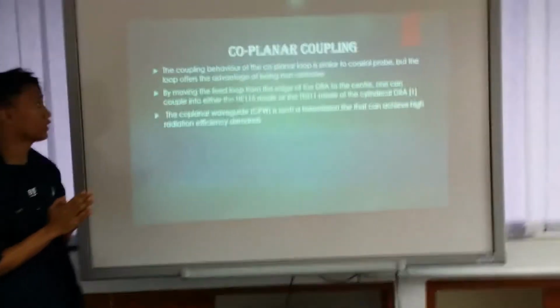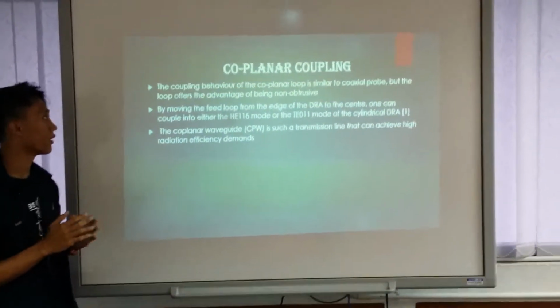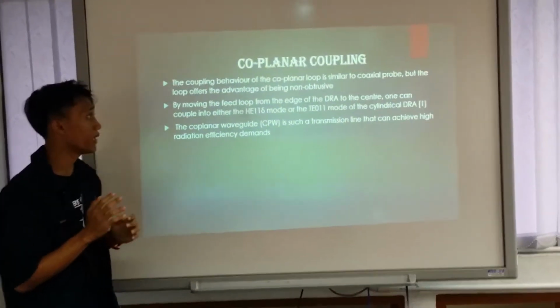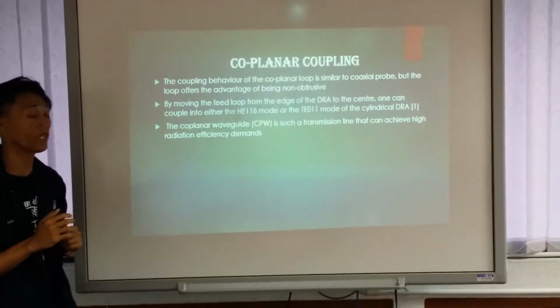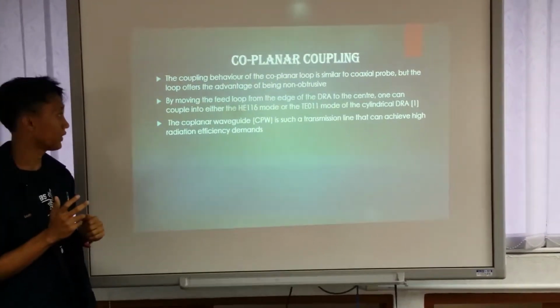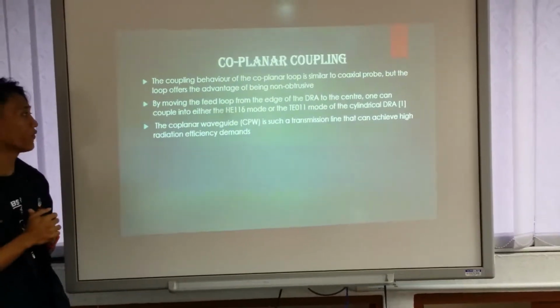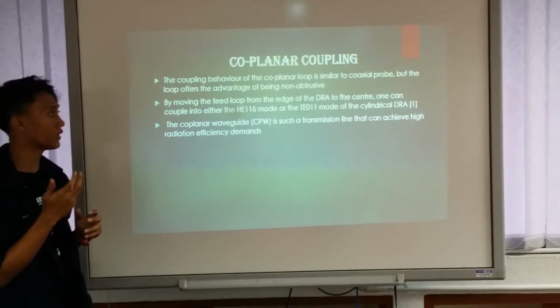And the last one is coplanar coupling. The coupling behavior of the coplanar loop is similar to the coaxial probe, but the loop offers the advantage of being non-obtrusive by moving the feed loop from the edge of the dielectric resonator antenna to the center.